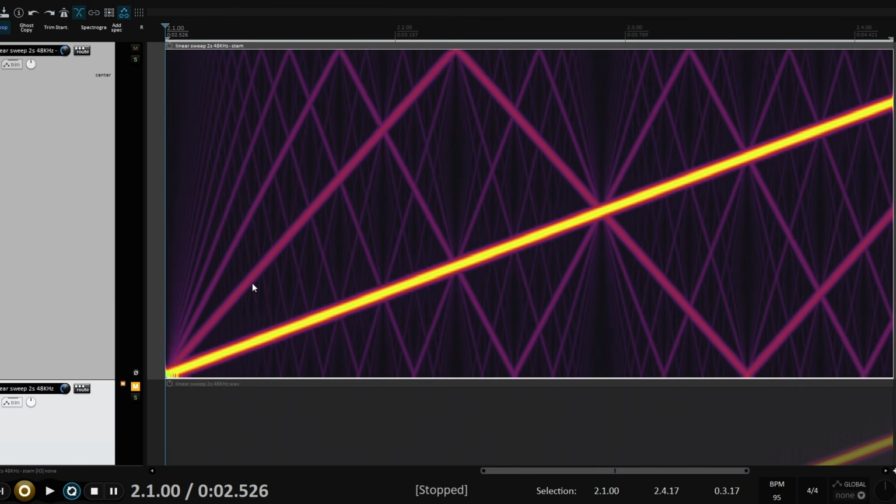What we're interested in is what happens when those harmonics hit the Nyquist limit at the top of the scale. They should just stop. That's what analog distortion would do. But in fact, they reflect back down again and sweep down in frequency until they reach 0, at which point they reflect back up again, and so on. That's aliasing.